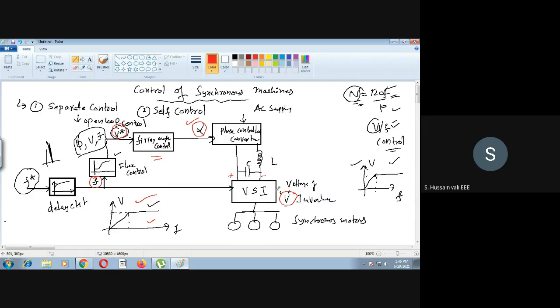So to get this voltage, what should be the value of alpha, so that this AC value will get rectified through this controlled converter? Then that rectified voltage will come here, then go to your voltage source inverter, then it generates this much voltage. So alpha is decided by this voltage, indirectly. Everything is related here. Okay, that's it.